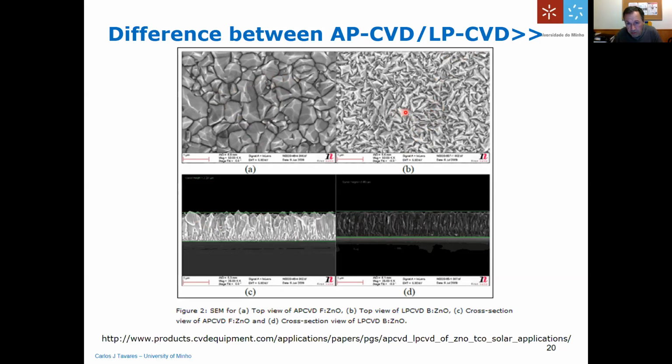Whereas here, from the low pressure CVD, you have films with more finite grain sizes. You also have a random distribution of these three-dimensional type of crystals. They grow in columns like in sputtering. Okay, you can see here from both cases, they start off from smaller crystallites. They have this kind of island growth which develops into columns that you see here. And as the thickness of the film increases towards the surface, these crystals become broader, okay?